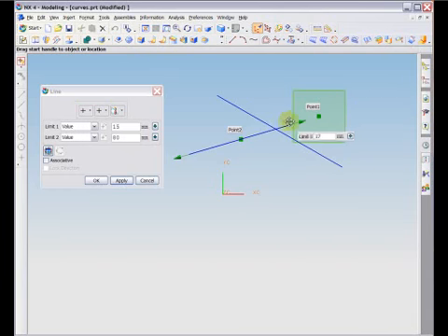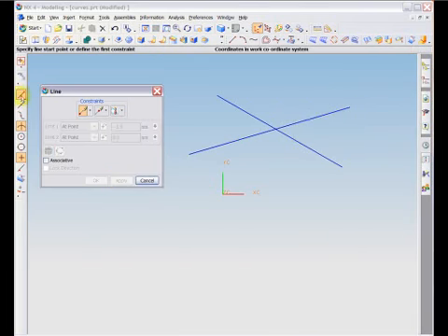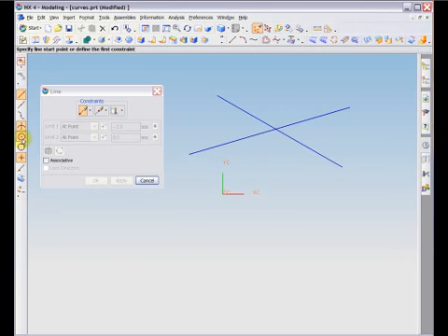The constraint options may be used to help you in inputting locations for start and end points. They can allow you to snap to locations with respect to existing entities. These locations can be endpoints, midpoints, intersections, etc. The options available are set by toggling the buttons on the icon menu on the left side of the screen. By selecting the appropriate buttons, you can specify which choices are allowed when selecting your start and end point.